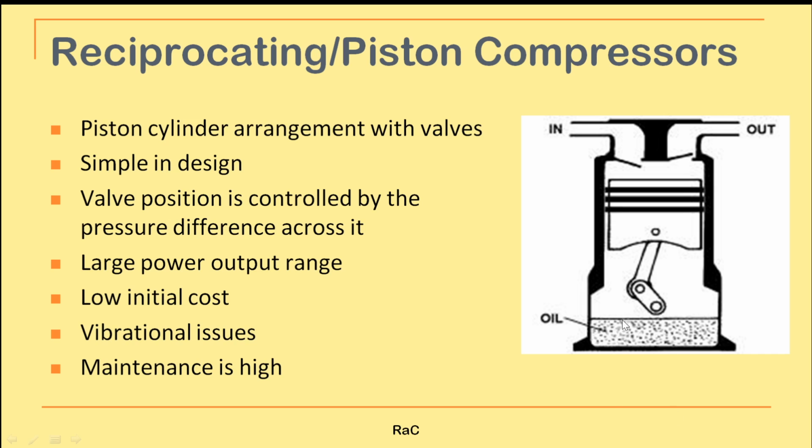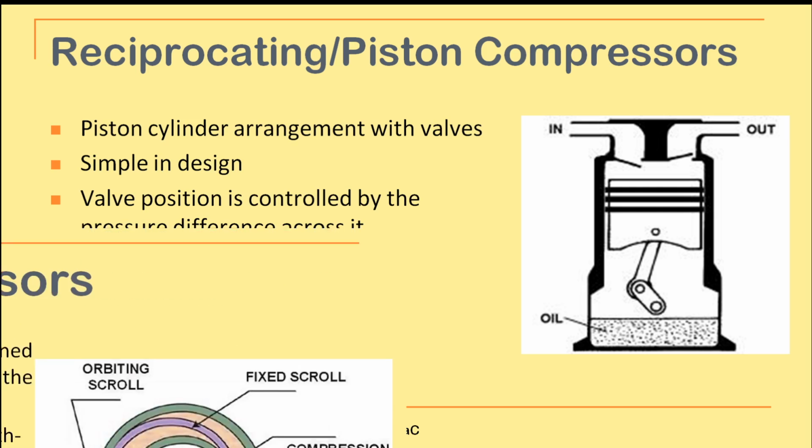So if at all this oil level is quite low, what will happen? There will be friction, heat generation. It will burn the piston rings, even gaskets, or the internal surfaces of the cylinder may get damaged. So from the maintenance point of view, it is not good.